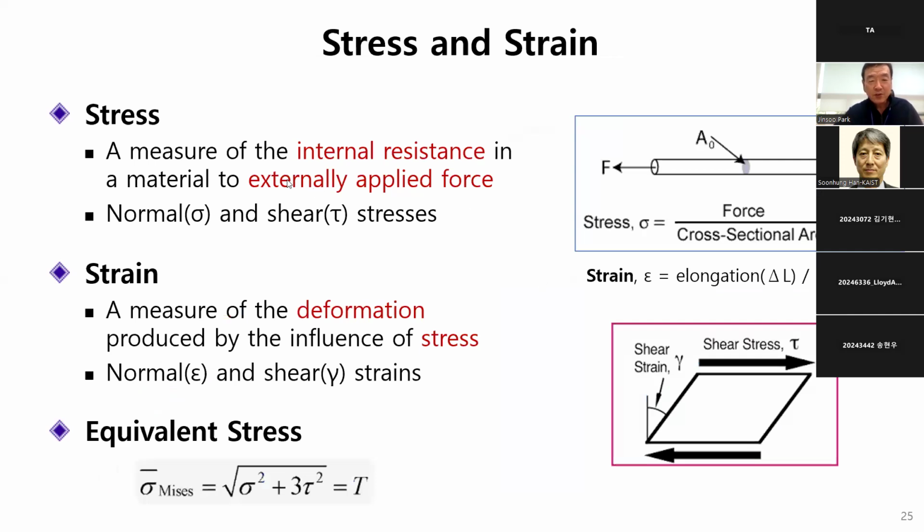The stress is a measure of internal resistance to externally applied force. Sometimes stress states are very complicated. There are many components, up to 9 components, but we use one equivalent stress to evaluate the stress state.